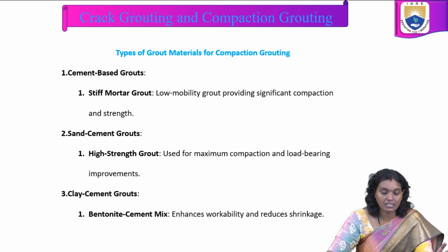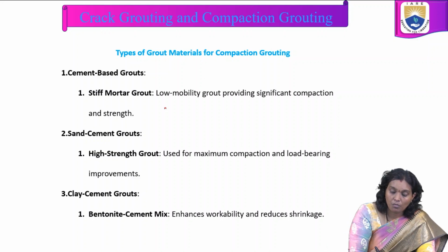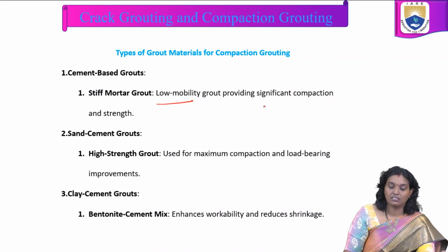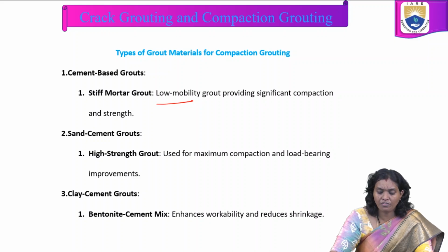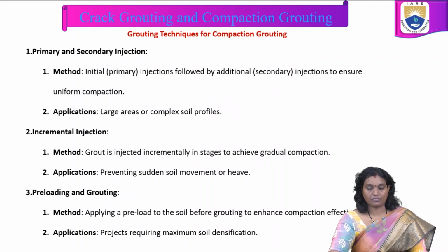In that, cement based grouts, sand cement grouts, clay cement grouts. In cement based grouts, stiff mortar grout, low mobility grout provides significant compaction and strength. The next one is sand cement grouts, used for maximum compaction and load bearing improvements. Clay cement grouts enhance workability and reduce shrinkage.